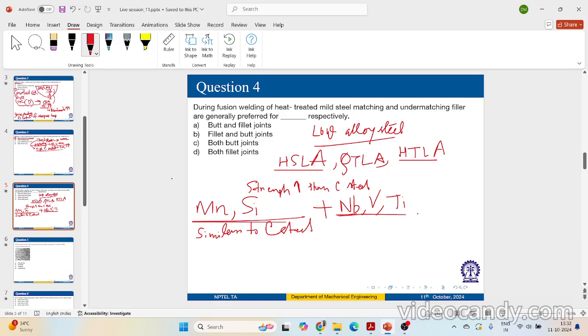They are grain refiners, these alloying elements. So in high strength low alloy steels, we add these alloy elements to ensure both grain refinement and precipitation hardening. So for these two aspects, these alloying elements will help in terms of precipitation hardening and grain refinement. They are also called microalloy steels. As I was saying, the alloy compositions will be very small, always in the range of 0.05 to 0.07% probably. They also are known as microalloy steels.